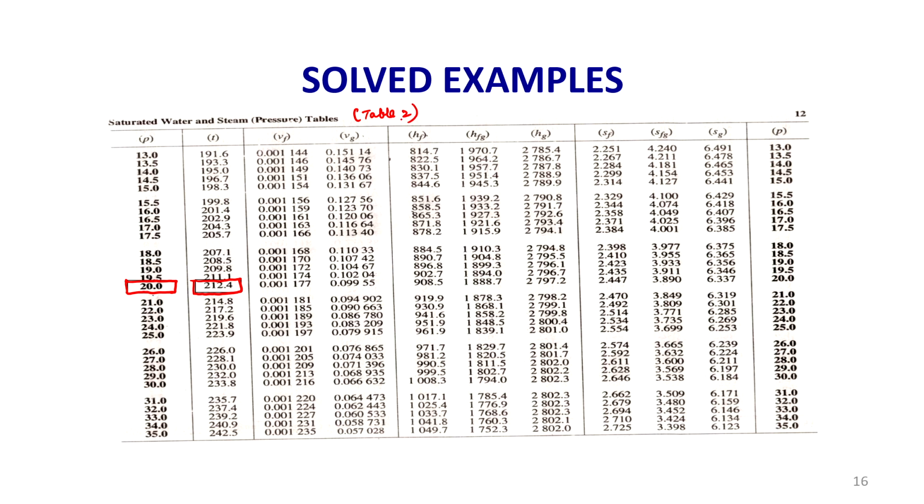There are 5 tables in a steam table. Table 1, first column is temperature, second one is pressure. Table 2, the first column is pressure and the second column is the saturation temperature. Of course, specific enthalpy, specific volume, entropy values are there in both table 1 and table 2. Then tables 3, 4, 5 are for superheated conditions.